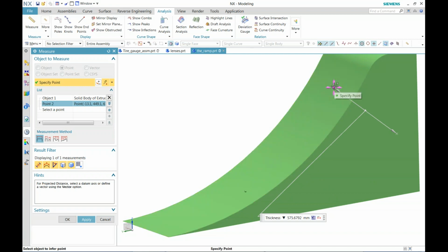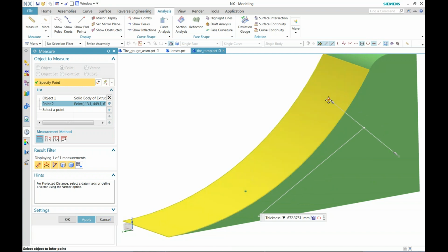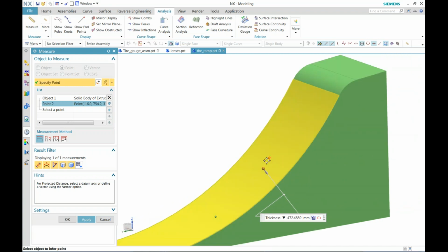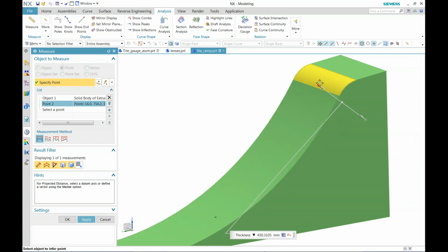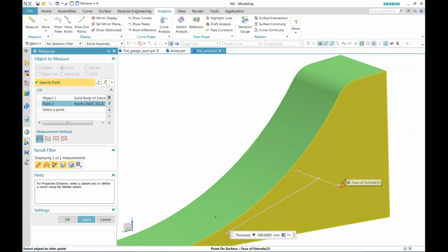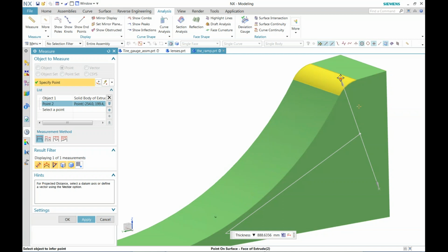And what's even cooler is that I can grab that ball and start dragging it around the surface if I want to, right? To start to see the thickness over the course of that body. In fact, it doesn't have to be on that face. If you remember, I just selected the body up front, so I can move around across faces, come the other direction. This one has a uniform thickness side to side out there, for instance. So that thickness probe is a new one.